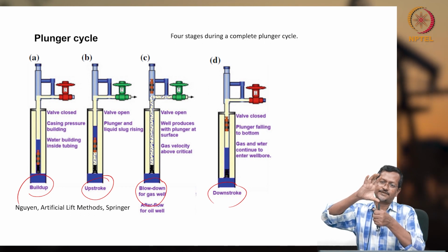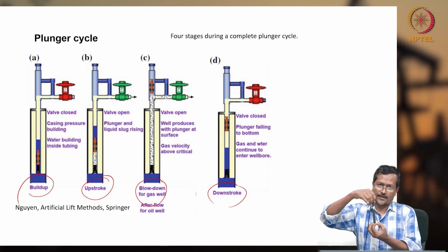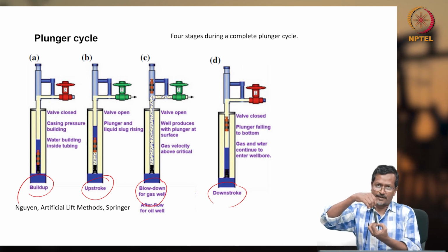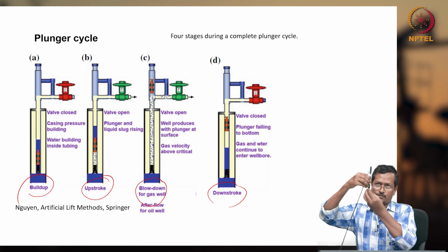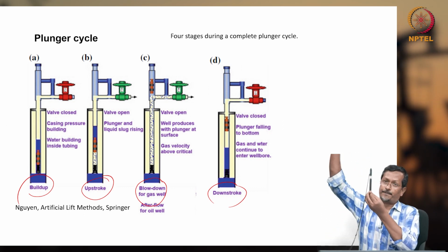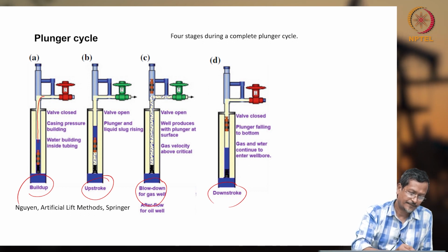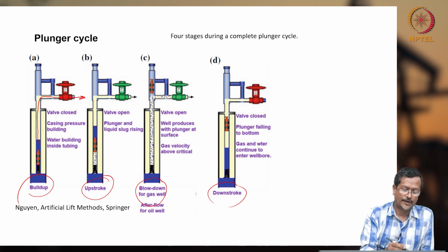After a certain time, when a certain column level is reached, you leave it with a very high force, because it was held by one spring, this is called the bumper spring. So, now you leave it and give some push. Because of leaving and pushing, the whole plunger will be moving up and all the liquid also will go up. When the liquid is going up, you see this picture I am drawing. Liquid will be moving through this. This will happen during upstroke only.